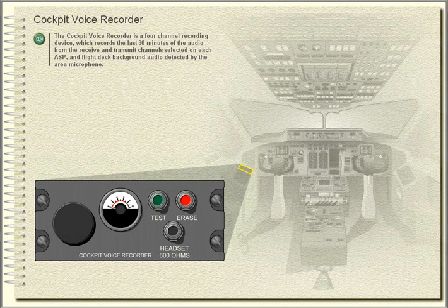Cockpit Voice Recorder. The cockpit voice recorder is a 4-channel recording device which records the last 30 minutes of the audio from the receive and transmit channels selected on each audio selector panel and flight deck background audio detected by the area microphone.